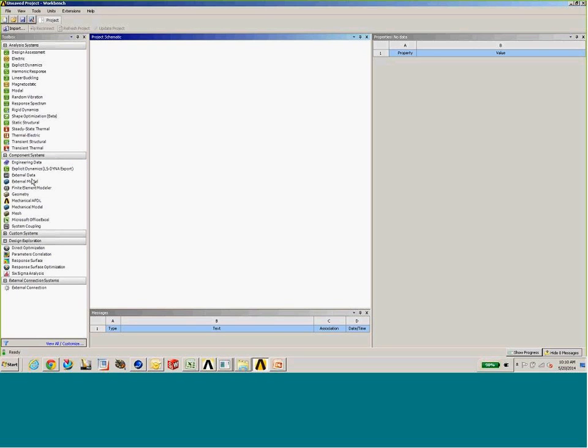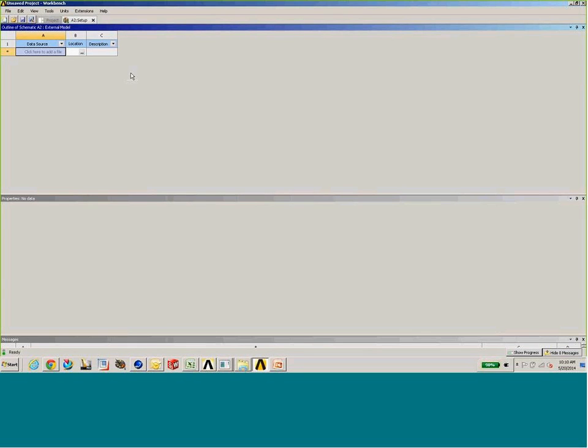and you'll find under the component systems there is now this utility, External Model. It's right below External Data. And it actually works very similar to External Data if you've had an opportunity to use that in the past. You drag it, you drop it onto the page. Zoom in on my plot here. Double click to open up the utility. And you'll see it's asking you to provide a file that you're going to import into Workbench.